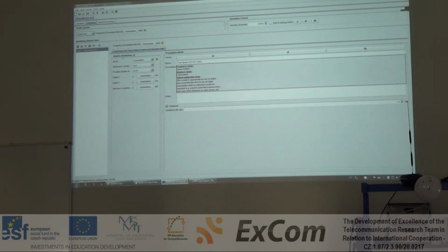Okay, and finally here the relative positioning. This is very important because here you will define how both systems are positioned between them. In that situation they are correlated, which means they are fixed between them. No mobility between systems. But you could define, for example, uniform, and in the uniform you can define a cycle when the systems can be moving, and you can also define the position inside this cycle, where one system corresponds to the other.